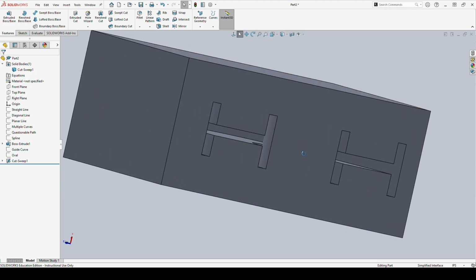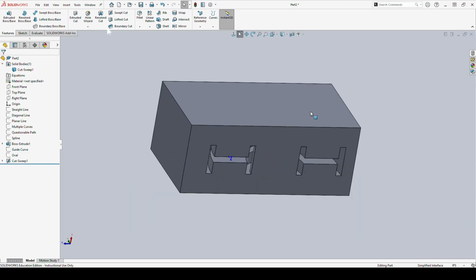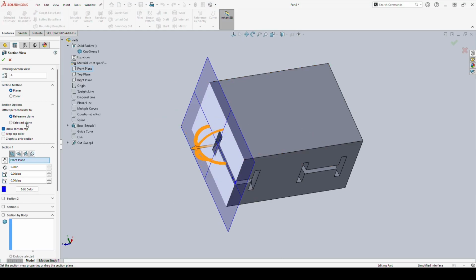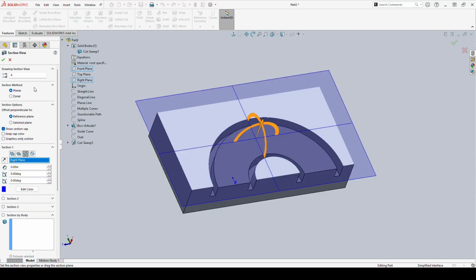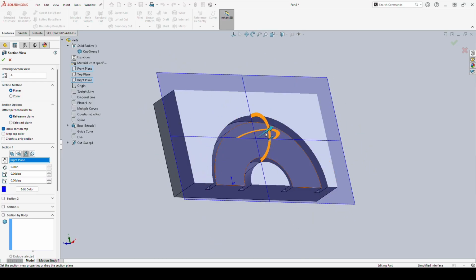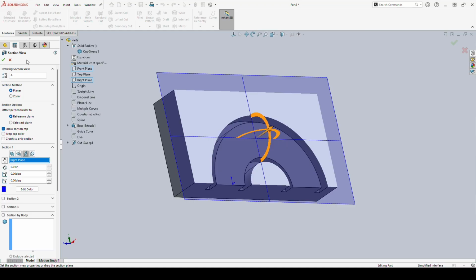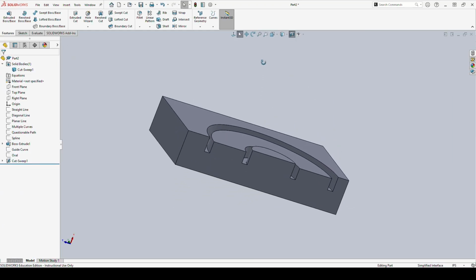Okay, just a brief reminder that once again, with all of our extrude commands, anything that adds volume, we can also use the inverse. So we have our sweep, add volume, and we have our swept cut, remove volume. And the inverse exists for all of these different pieces. So this basically followed my path, and we have created a cutout within the shape of the eye curved along here. In this case, I probably could have used revolve cut, but again, this would work just the same as our adding material, just inverted.